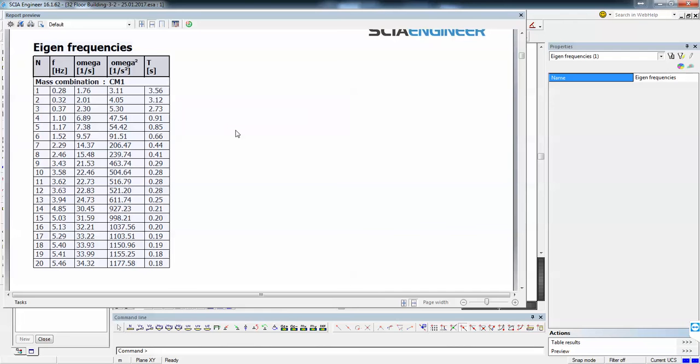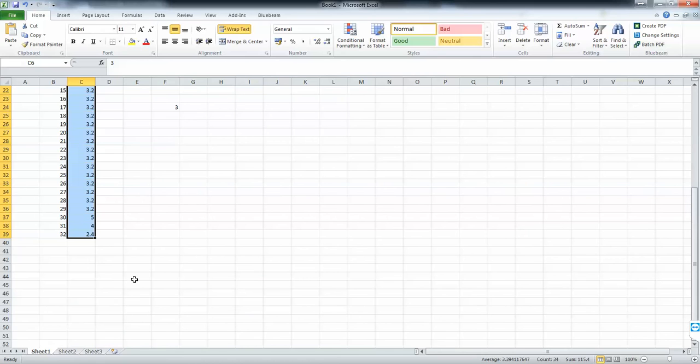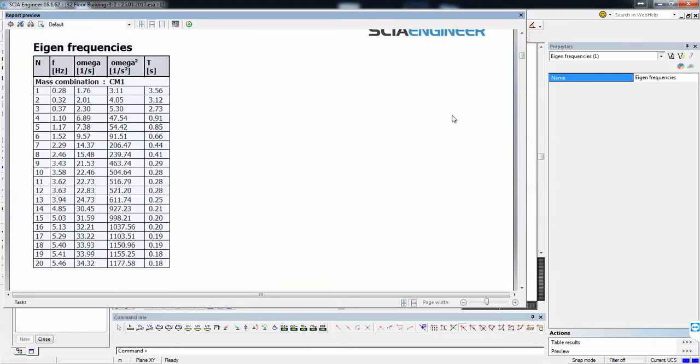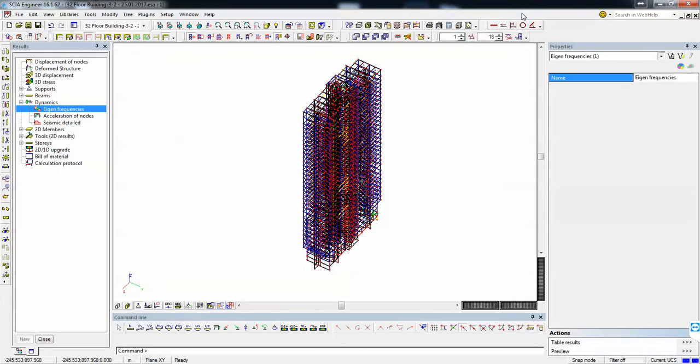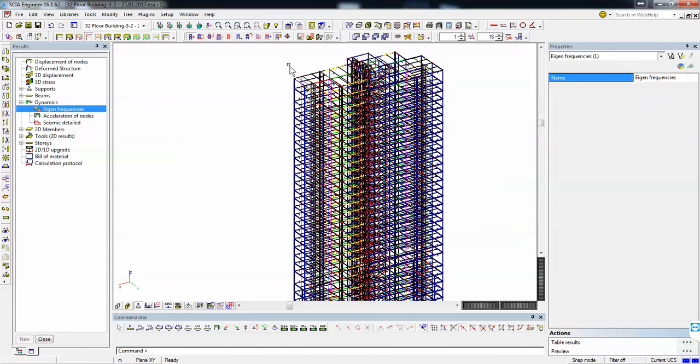And if we think of the number of stories you have, if we add this extra 2 to the 32, it's almost perfect. So it's a good period. This is only a qualitative and not a quantitative assessment of the building.